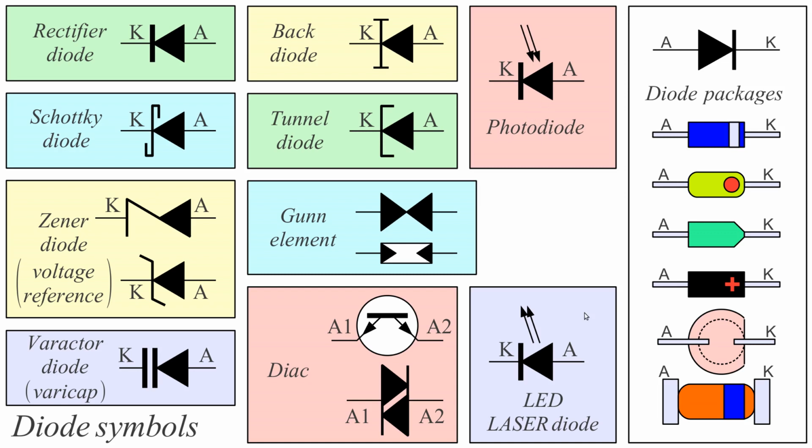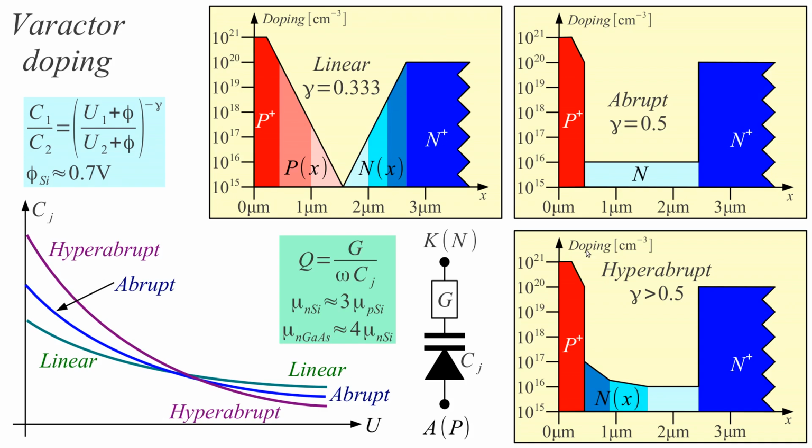Diodes made of some materials may also emit light, like light emitting diodes or laser diodes, but here silicon is a bad choice because it has an indirect bandgap. Here we should use a 3-5 semiconductor that has a direct bandgap that does not require a phonon to be generated, but most of the energy that's released with a recombination of an electron and a hole is released as photons, so as light. So here silicon is not a good candidate. But even today LEDs and lasers, we use them in most of our communications, especially over optical fiber.